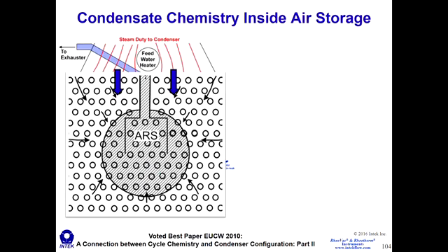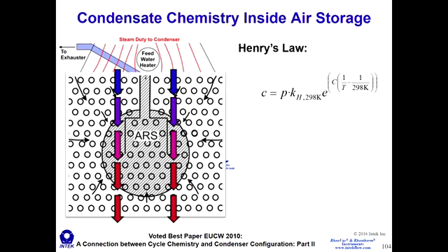And so the condensate that's formed on the outside of these tubes above the stagnant zone falls down and enters this region of high partial pressure of air. Now, these colors don't represent a temperature change, but they represent the increase in dissolved gases in the condensate. So there are no dissolved gases in the condensate up here, and as they fall through this zone, there are dissolved gases in the condensate. And we can quantify that.